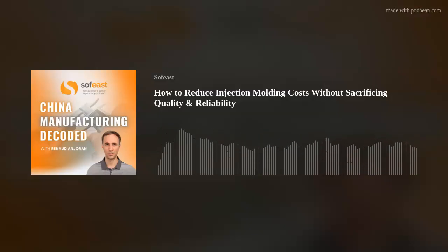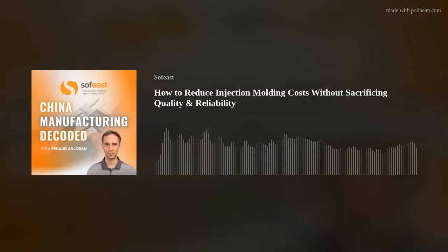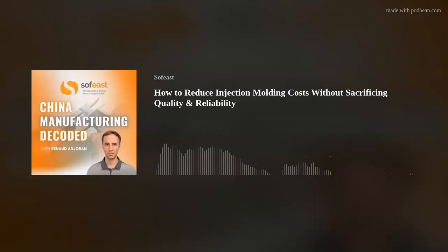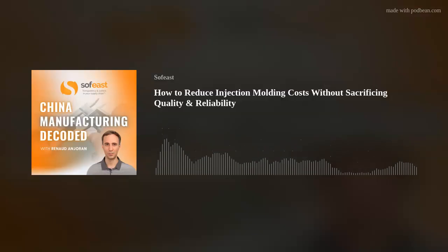All right. So I am the guy that's the startup, and I'm not too sure how things are going to go, but I'm assuming that my business is going to go through the roof. Do I go with a 32 cavity tool, or should I go with a 1 cavity tool, or maybe a 4 cavity tool? Well, I certainly would not go for a 32 cavity tool because that's going to cost you a lot more.